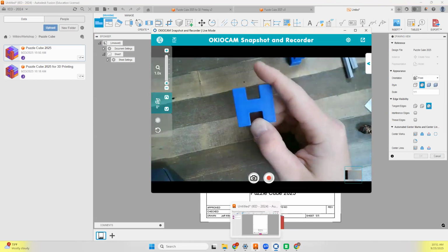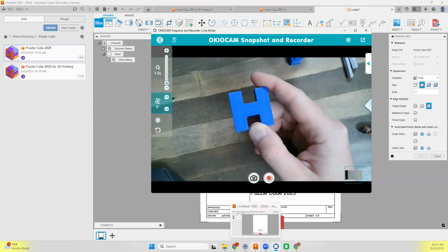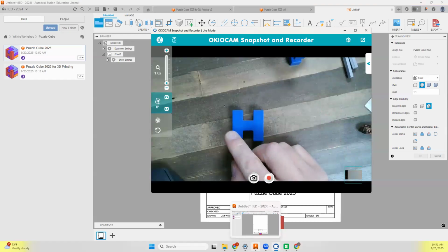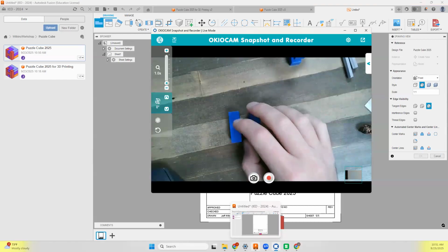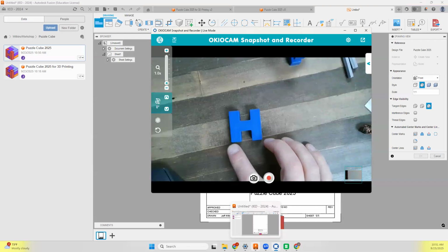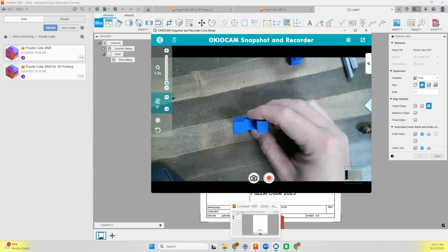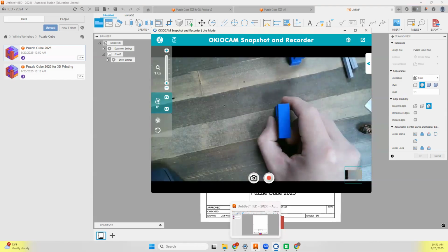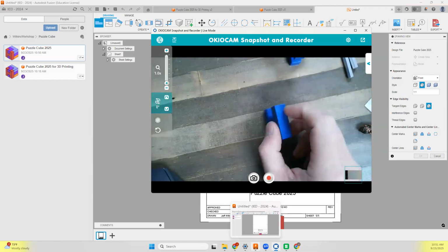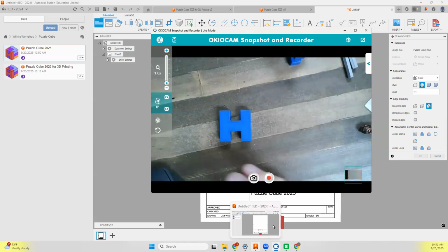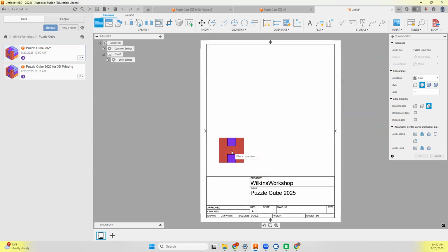And the best front view would probably be in this orientation right here. You want the most contour, most detail, longest dimension typically for here, and least hidden lines. Again, you can't get away from having hidden lines there, but that's going to be my best front view. That's why we're starting with the red piece.